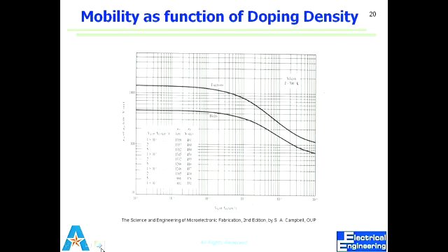So in CMOS, if I have an N-type substrate, a heavily doped P-type resistor will do the job. Makes sense? It's called degenerately doped. Above 10^20, 10^22, or 10^23 is called a degenerately doped semiconductor. We will not even talk about symbols, but we'll talk about fabrication only. That's it.